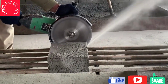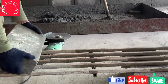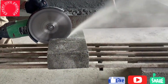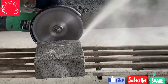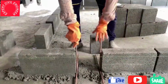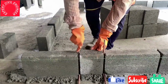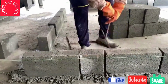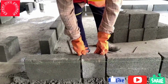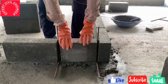Using the cutting machine, the blocks should be cut according to the required size which was measured previously. The measured block needs to be arranged in the left gaps. Once the measured blocks are arranged, the alignment needs to be thoroughly checked.